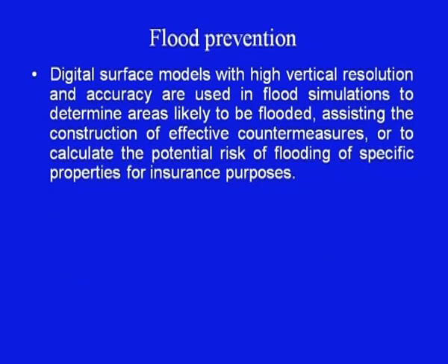For flood prevention, digital surface models with very high vertical resolution and accuracies are used in flood simulation to determine areas to be flooded, assisting the construction of effective countermeasures, or to calculate the potential risk of flooding of specific properties for insurance purposes.